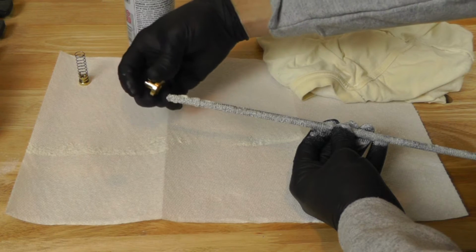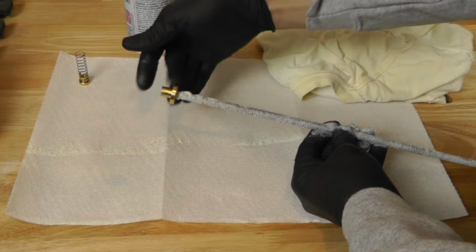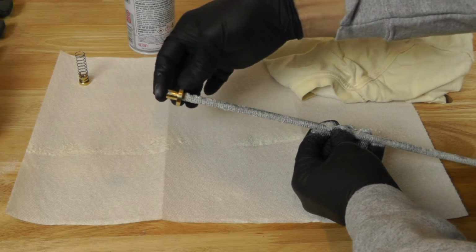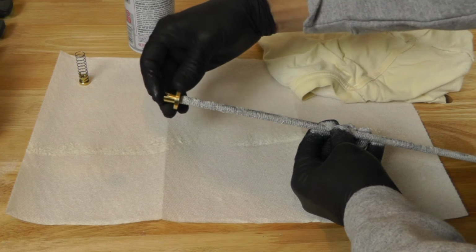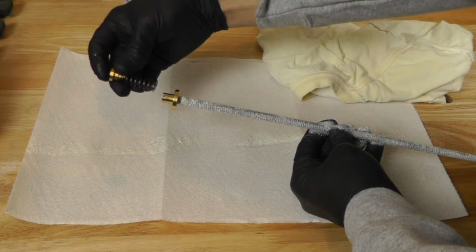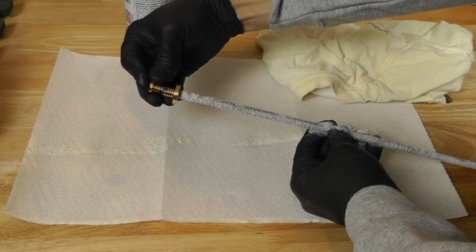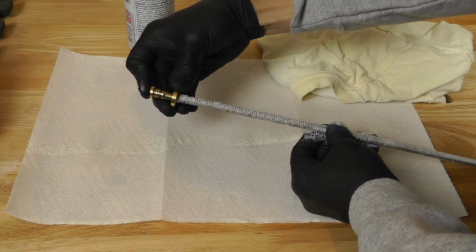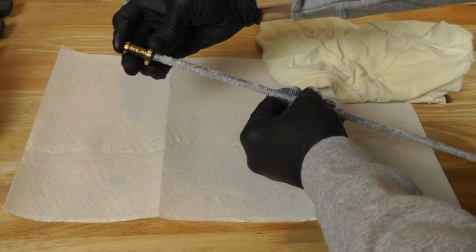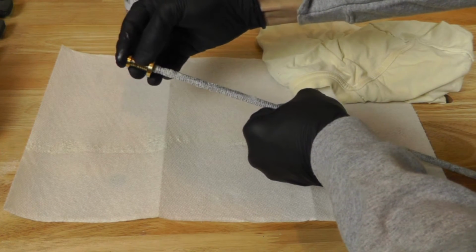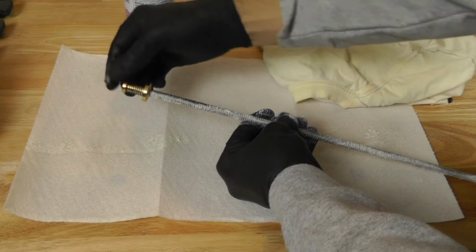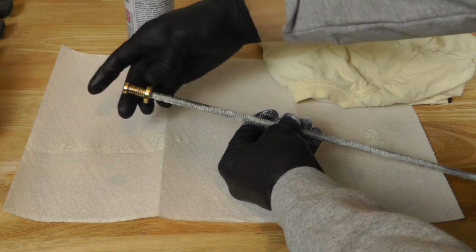So now I have my new anti-backlash nut. I'm going to put the head of the nut on there. And in order to put this on properly, you need to leave just this little notch on the top part hanging off the edge. I'm going to take my bottom with the spring already on it. I'm going to push it all the way down as much as I can, and then try to get it threaded on at the same time. And it may take a little bit of work to get it right where you want it. But once you have it on there just right, try to get it as tight as you can, but with a little wiggle room so that it still moves.